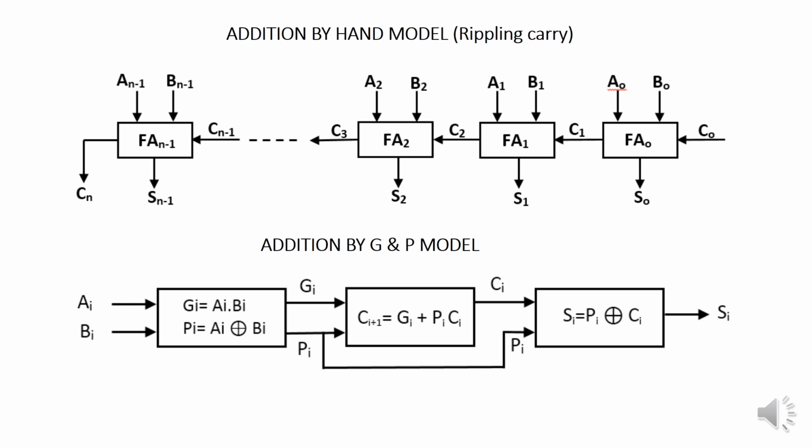Also, from the start, each full adder block is ready to operate, but to complete the sum has to wait for its corresponding input carry to come. So, in the ripple adder, the carry propagation is more critical than the sum. The maximum arrival time goes obviously all the way through the carry's propagation until the sum of last bit.